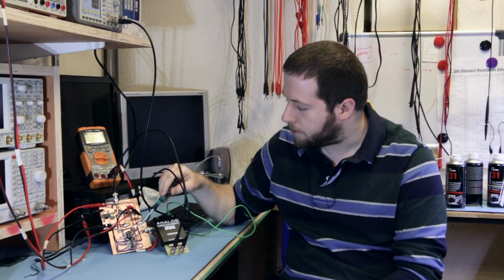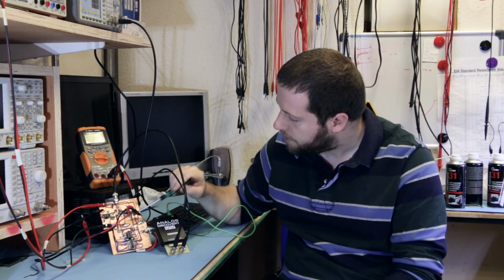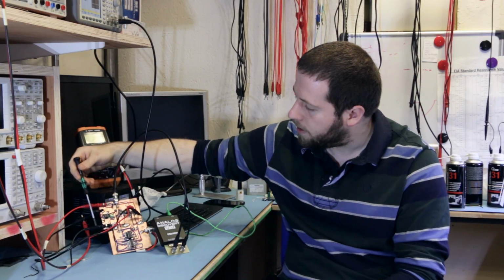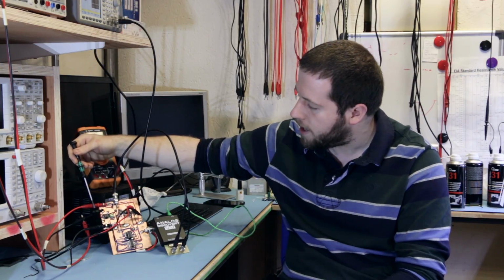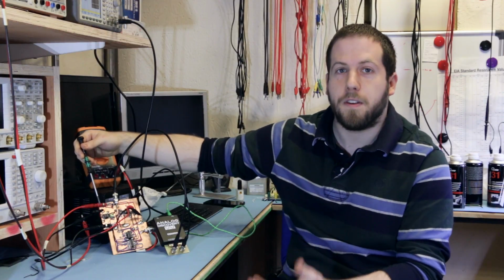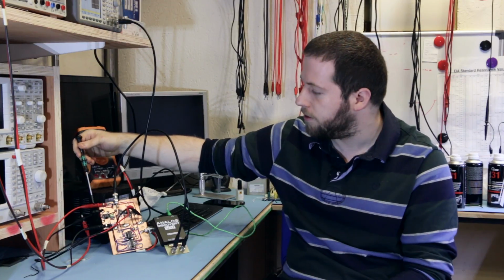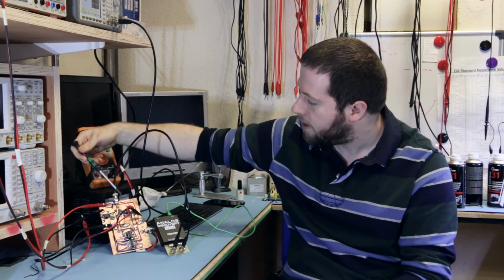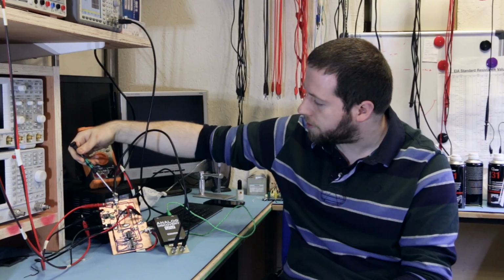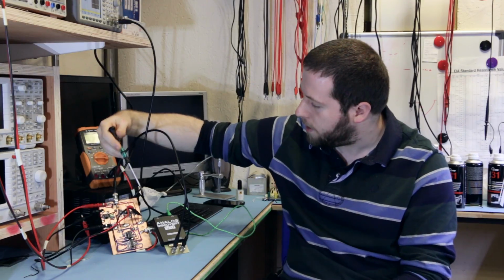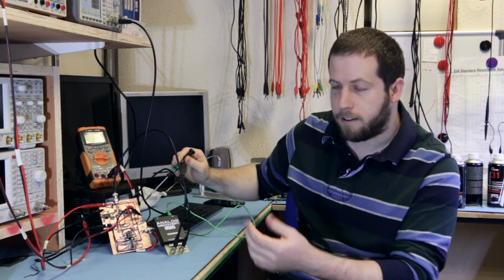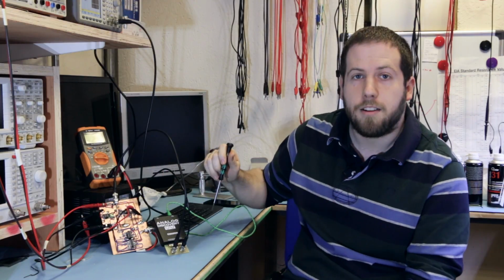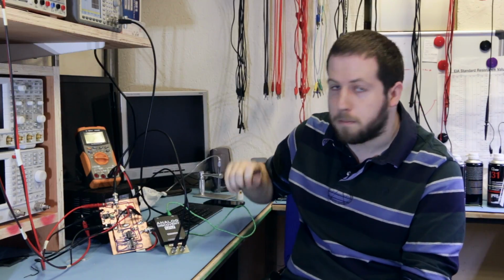Lots of decoupling caps, especially as we've got split rail supplies on this. And then, as before, we've got the power supply coming on here. So this is now full plus or minus 15 volts. We're now not limited by the switcher rails, that was just because of which switch ICs I had in stock. Again, we've got the Analog Discovery input hooked up to here, and then we've got the output, currently connected up to the low pass output, and we just move that around the board. So we're all ready to set this up and take some measurements.